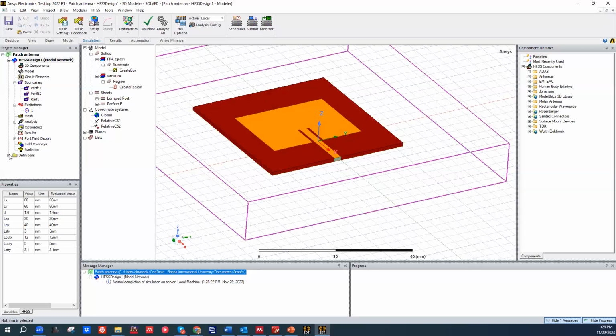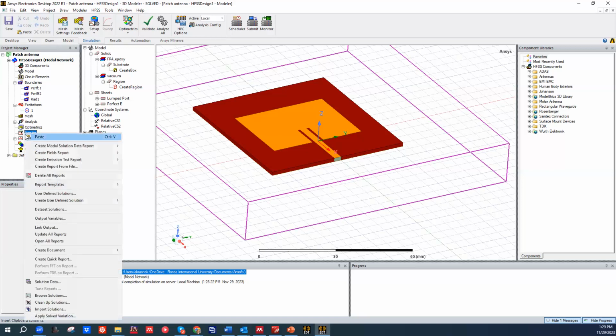So it basically gets two main parameters, right? The first one is how the antenna transforms the waveguiding mode to the free space radiation, and it's characterized by the S11 parameter, or reflection parameter. And this parameter characterizes the transformative properties of the antenna, right?